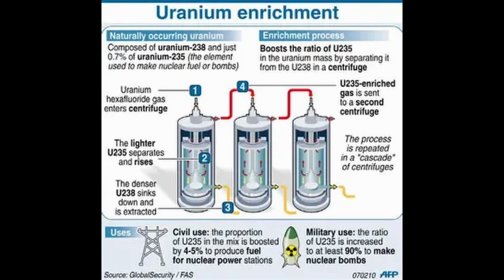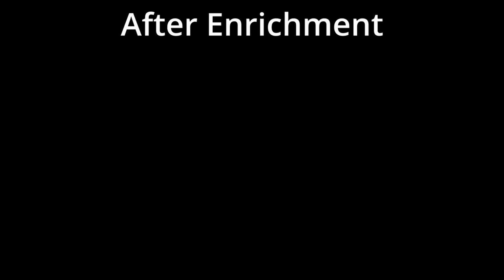The gas is placed in a cylinder and rotated at a high speed, and then the centrifugal force creates the heavier molecules like the U-238 to move to the outside, while lighter molecules such as the 235 collect closer to the center. Then the gas closest to the center is withdrawn and fed into another chamber, and the process is repeated until the desired concentration is acquired.